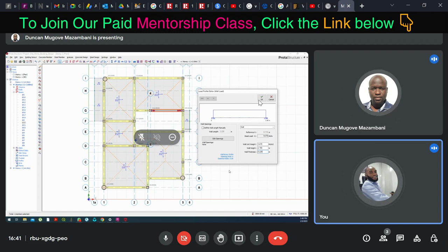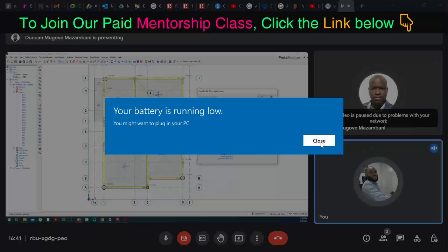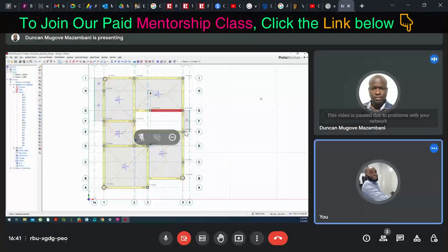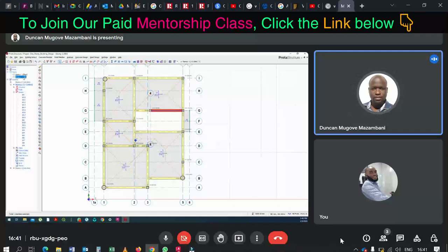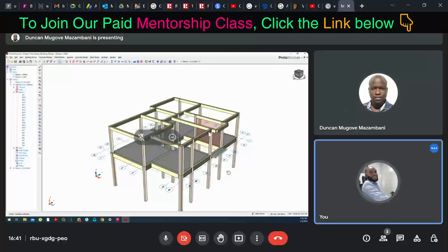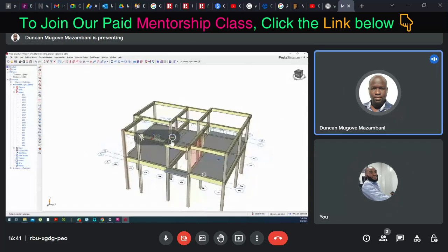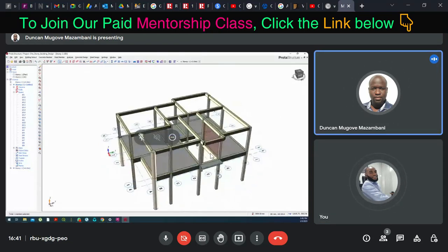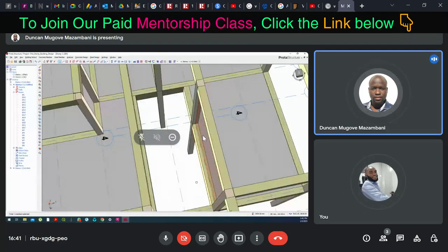Okay, so with this I can now say okay. Once you say okay, that beam will now highlight as having a wall load. If you check your 3D view right now, you see that the beam has a wall load. Okay, now go back to your plan view. As you can see, there's a wall load symbol, the red one, with the dashed line here. Yes, that shows that the beam has a wall load.